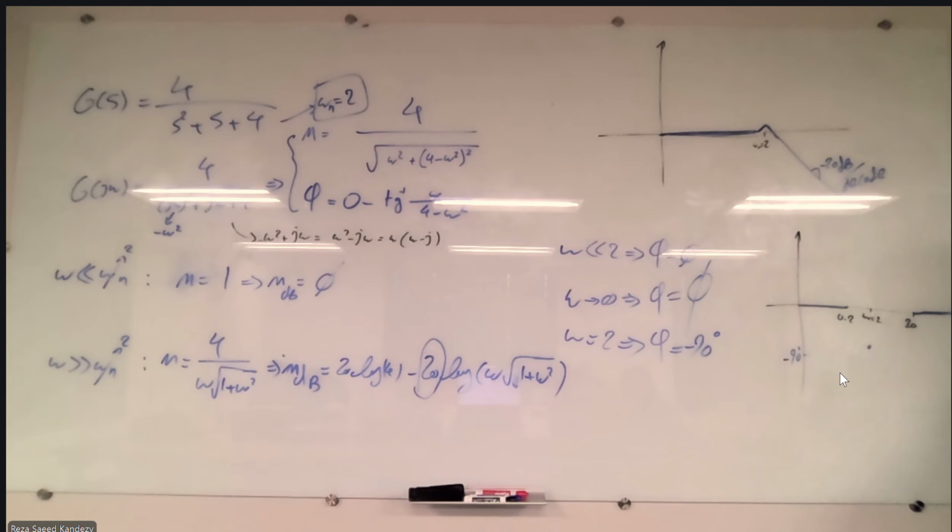So what's going to happen? We are going to end up in a decrease. You can consider the asymptote line with two slopes, okay, which is minus 90 degrees from 0.2 to 2, and plus 90 degrees per decade from 2 to 20, okay, and then we have our phase values.